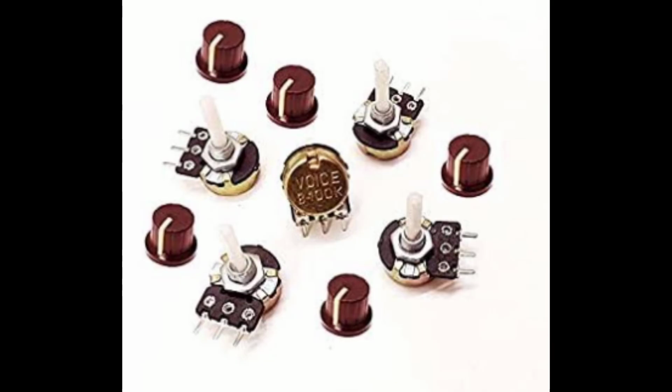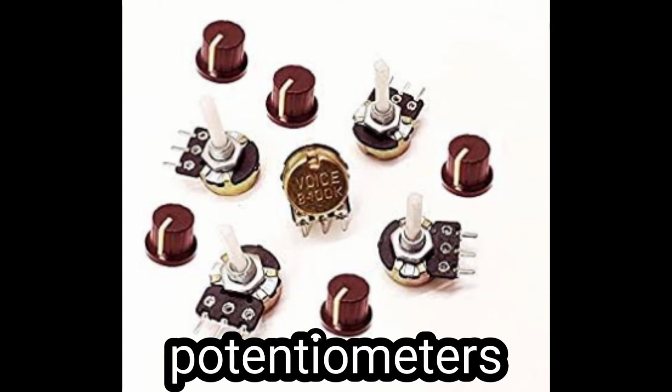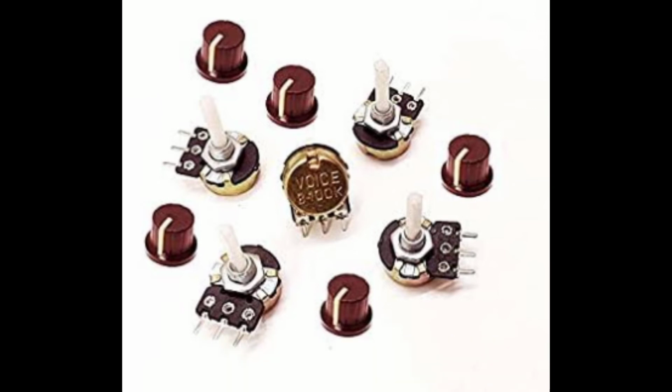The variable resistors are the type of resistor whose resistance can be changed manually by rotating the knob of a variable resistor. Most commonly used is a potentiometer. A potentiometer is a three-legged electronic component which is used for controlling the voltage in a circuit. The resistance between the rightmost and the leftmost leg is constant, while the middle leg is connected to the moving part called wiper.